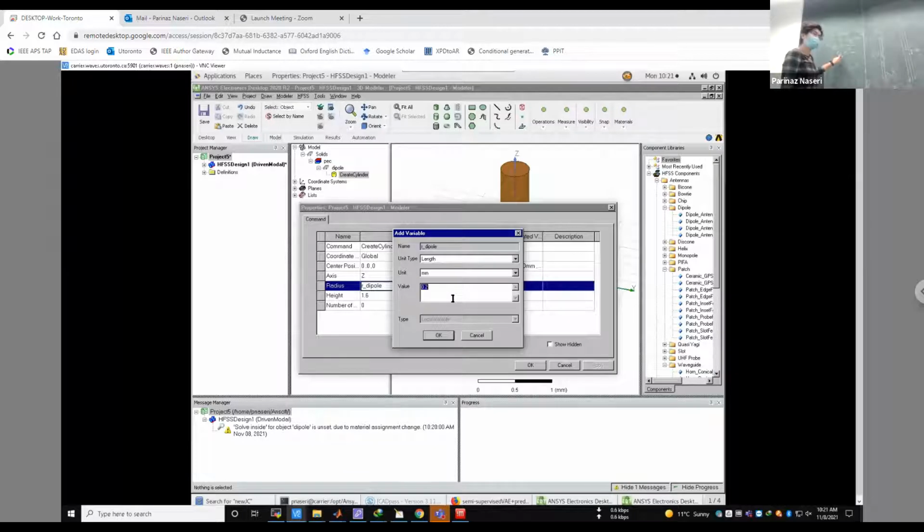Is this going to give you exactly what you need at 10 gigahertz? Exactly? No, you have to cut a little bit. Why? Because of edge effect, fringing fields from the edge, right? Okay. So anyway, the first rough calculation tells us that if the dipole length L is 15 millimeter, it's almost lambda over 2 at 10 gigahertz. And that would mean that it would resonate, it would have the input impedance of how much?